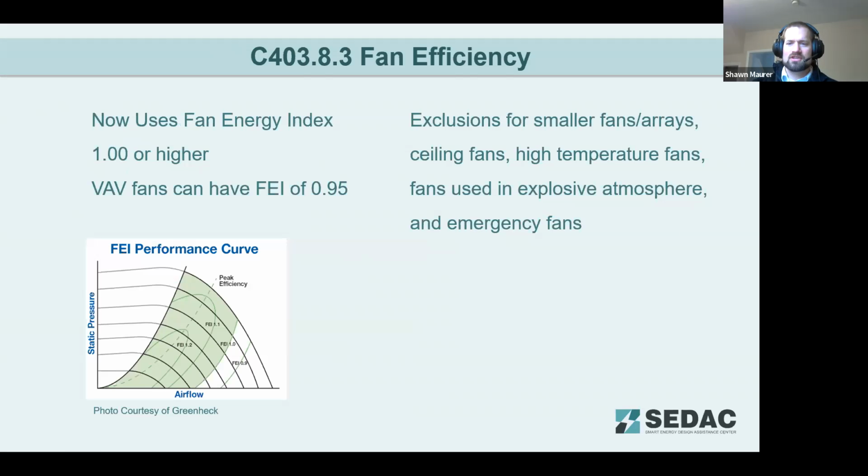And then our last major update to the IECC is the change in fan efficiency requirements. The 2018 IECC used a fan efficiency grade. What they noted with those types of systems is that you could have fans with the same efficiency grade applied to different situations, VFD versus not a VFD, belt drive versus a direct shaft connection, different changes to the layout of fan systems, where you would get dramatically different energy performance for the same fan efficiency grade.